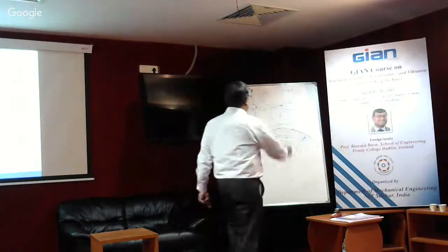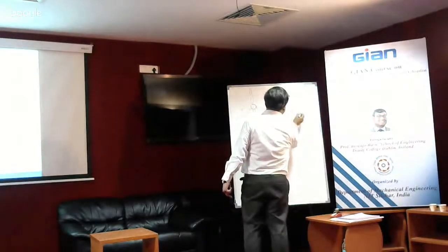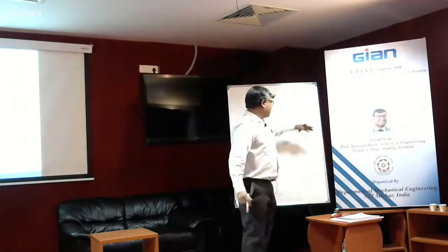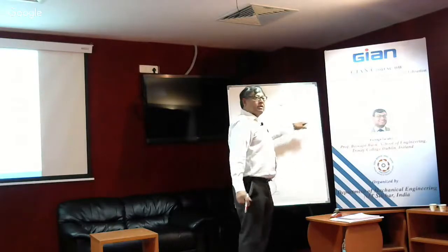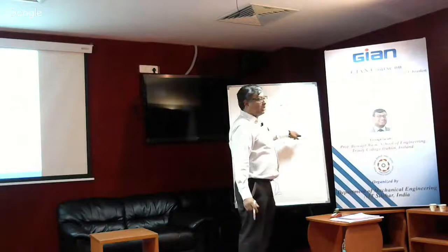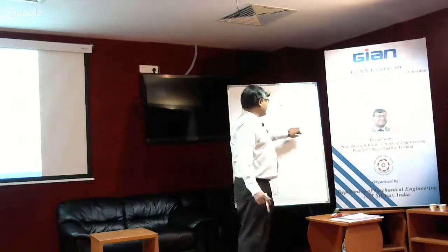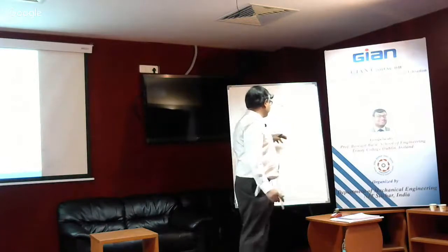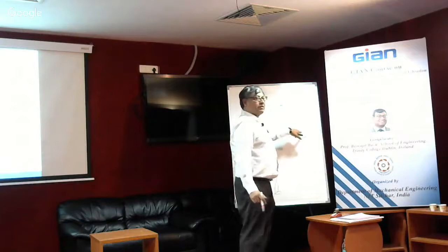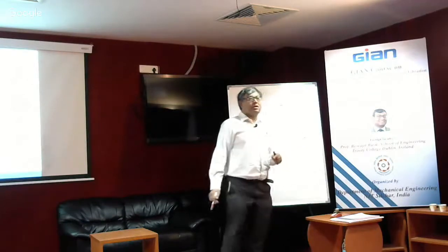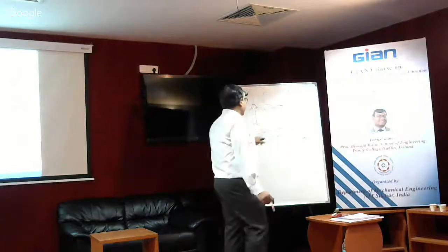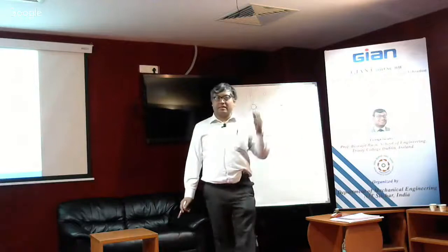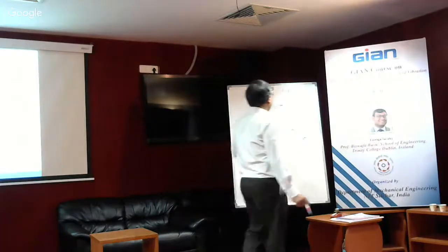Because when the wind blows, there's a small thin layer which gets attached to the surface. This viscous layer, but then that actually gets detached. Detachment causes some kind of wake, not really turbulence, but eventually may lead to turbulence. So this is where some energy dissipation may take place. This wake effectively means that if you have this velocity here, there is a portion where you have some pressure which is actually lower than ambient pressure. So effectively, it has a structure of flow like this. And when this happens, the lift actually then decreases.